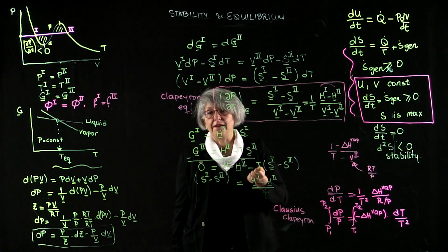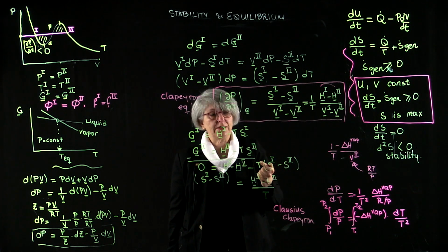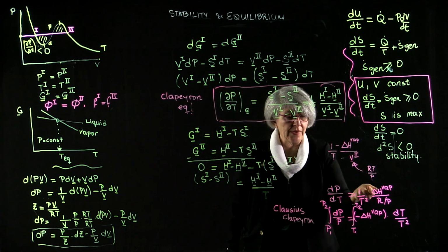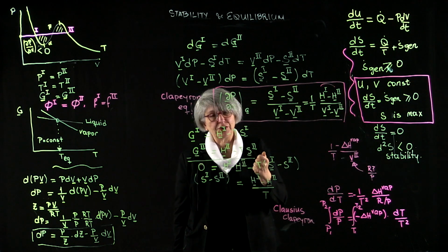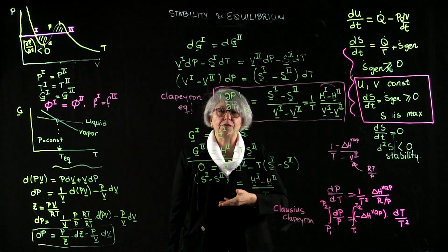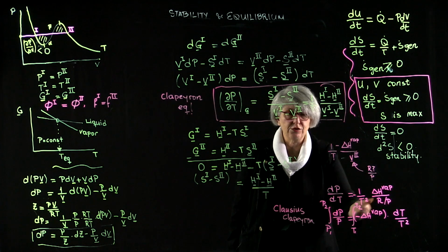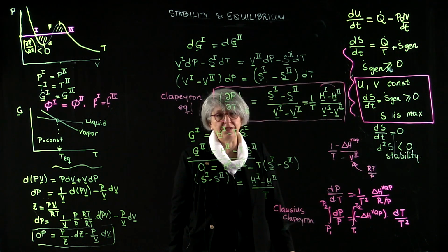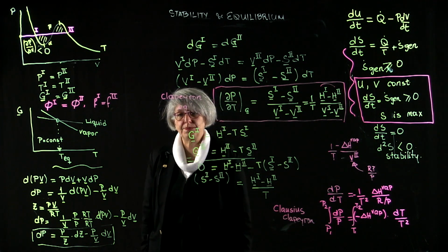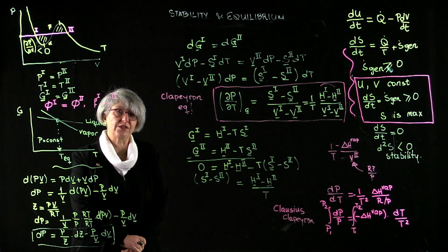If I have the enthalpy of vaporization of the fluid, and if it is independent of temperature, of course, or pressure, and if I know the vapor pressure of the fluid at one temperature, I can estimate the vapor pressure of that fluid at any temperature. All right? So this is a useful, convenient equation that we use in making vapor pressure estimations. So this wraps up the 7th chapter of Sandler.